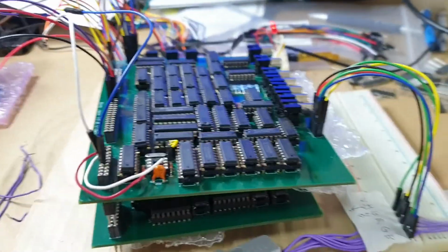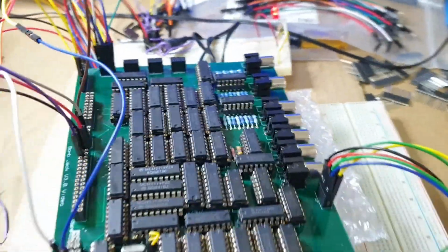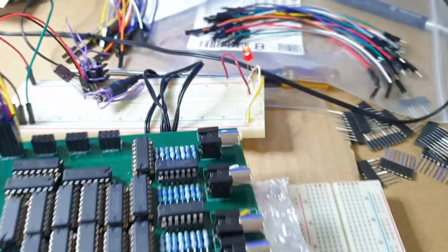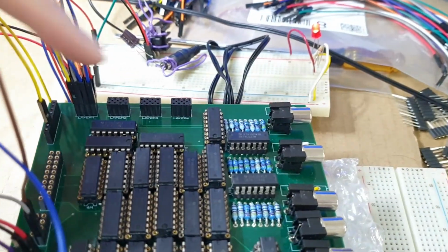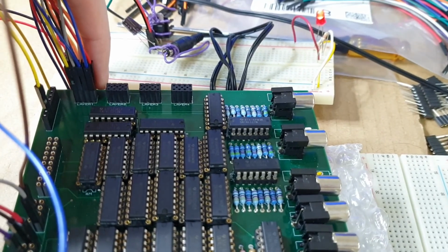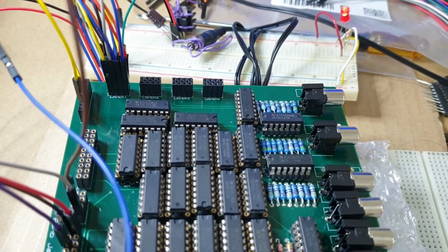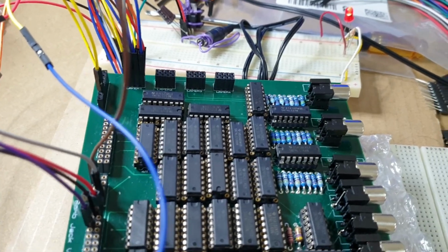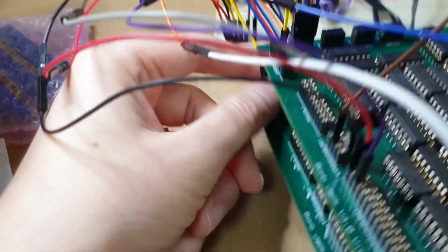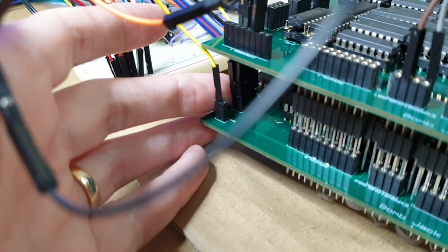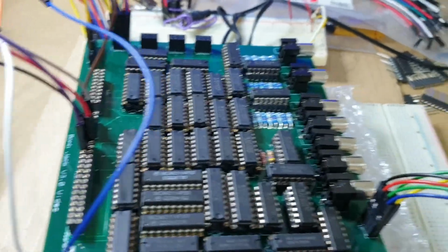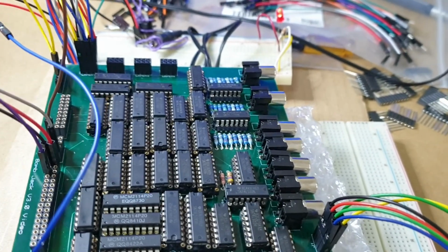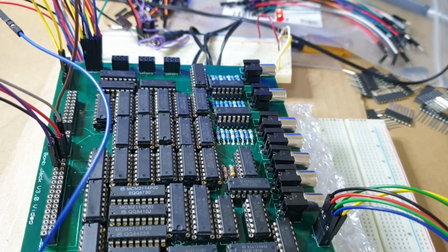Now, the next revision of this board. Oh yes, so things to note for next revision. Thing number 1 is these pixel headers here need to have the same arrangement of input lines as the pixel header on each of the boards here. At the moment, really annoyingly, they are reversed, which makes it really silly for connecting these up.